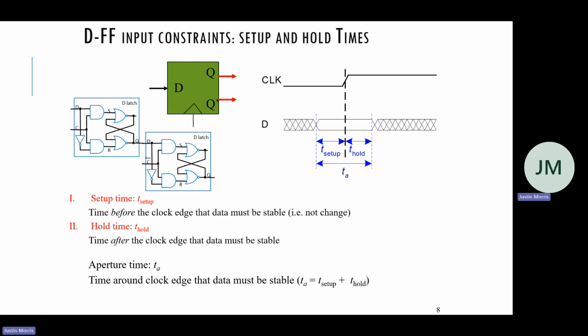Yes. So instead of the clock signal automatically going up, down, you would have like a line, right? Yes. It's not instantaneous. So that's what this whole time is for. So it's not just the clock that takes time, but after the clock changes, these AND gates also need to evaluate.